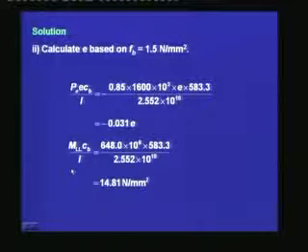The stress due to the live load is equal to 648 times 10 to the power 6 times 583.3 divided by the value of I, which is equal to 14.81 Newton per millimeter square.